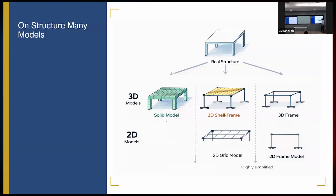So anyway, which is the next best model? This is the current choice of ETABS and other people. They model the slab by shell element and columns by frame element. This is our best approximation at the moment because it gives you what we need. This is what we used to do, and this is what ETABS used to do before they had shell element, which was not long ago.